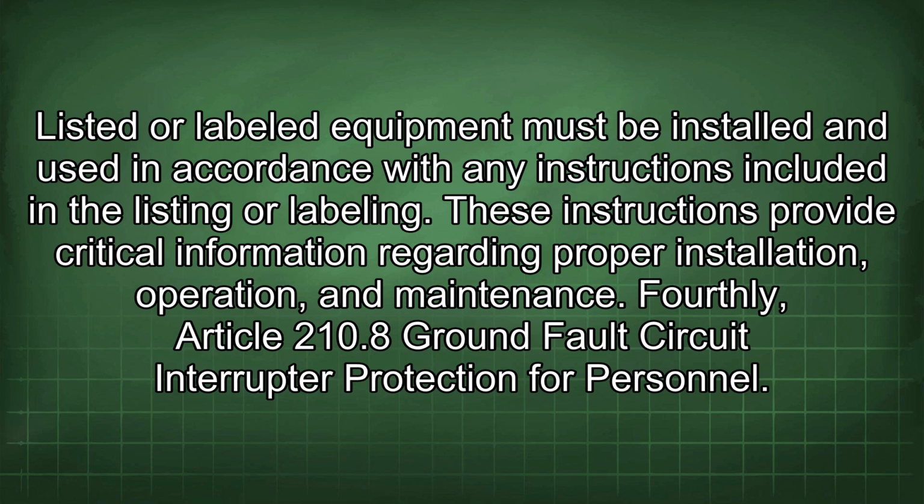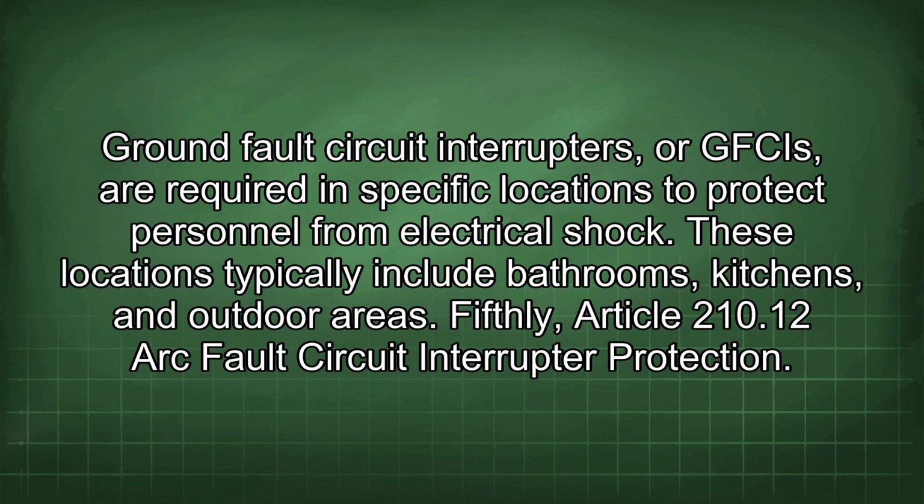Fourthly, Article 210.8 Ground Fault Circuit Interrupter Protection for Personnel. Ground fault circuit interrupters, or GFCIs, are required in specific locations to protect personnel from electrical shock. These locations typically include bathrooms, kitchens, and outdoor areas.